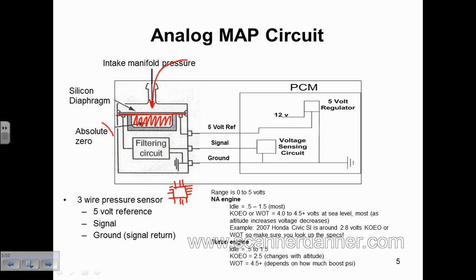They call that absolute zero. What's absolute zero? When you guys had air conditioning, you learned that is a complete absence of atmospheric pressure. We have gauge pressure, and then we have absolute pressure. So when our gauge reads 0, is it truly 0? Or is it gauge 0? It's gauge 0, right? And 0 to us is what we're around right now. No pressure, but that's false, isn't it?